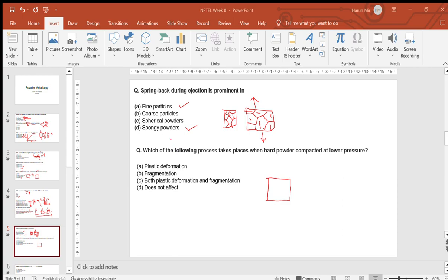You can say the green strength for case 1 and green strength for case 2 is equal to the pressure in the first case and the pressure in the second case. That will give the relationship between the strengths. We know the pressure of case 1 is 20 and for case 2 it is 35. So this is your relationship, 20 by 35.